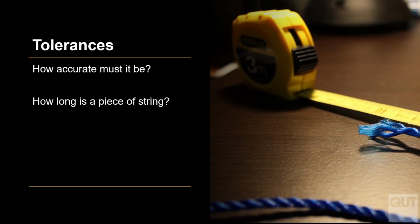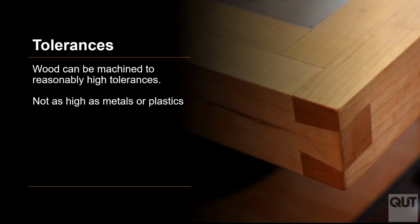So how do we set tolerances? Well, as I said before, the more tightly held a tolerance is, the more expensive it's going to be. But this depends very much on the manufacturing process that's being chosen and the materials that are being chosen to be manufactured. So for example, wood can be machined to a very high tolerance, but it's not as high as metals or plastics. Maintaining a very tight tolerance is not easy.